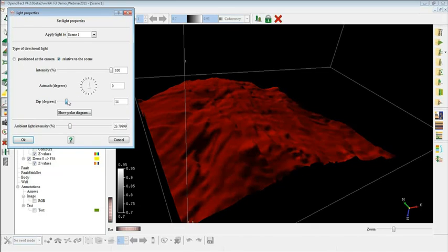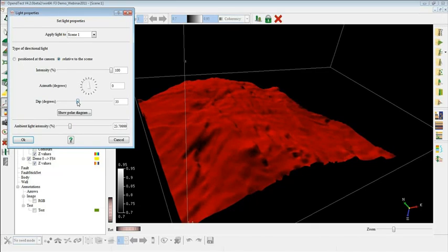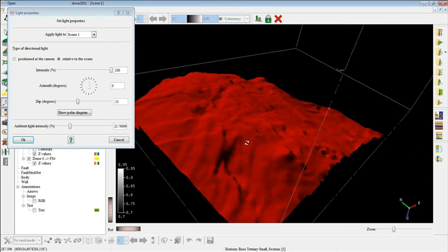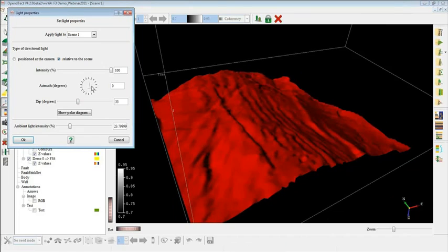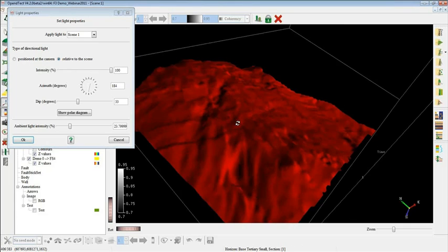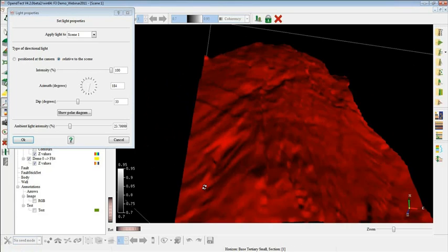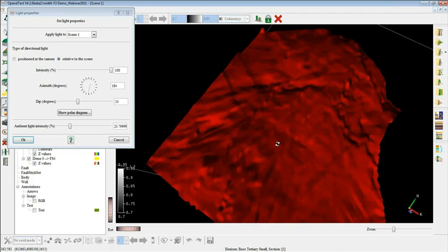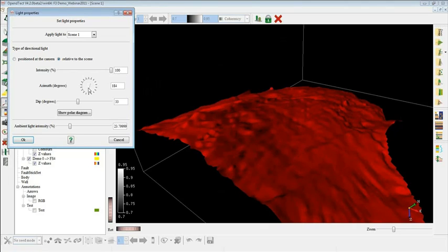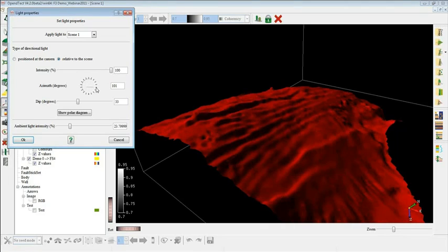You put it at a right angle for this view, and then you can change this knob by rotating the azimuth. Once you change this, you highlight the features very nicely. You see there was a nice channel running in here, and if I go to the opposite side, like in here, there were faults, but they're not appearing there, so I can put a nice azimuth there to illuminate these faults.